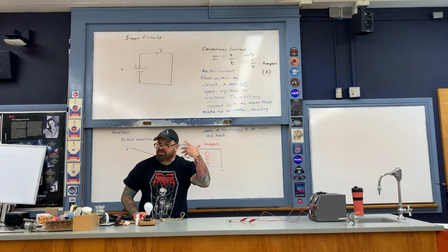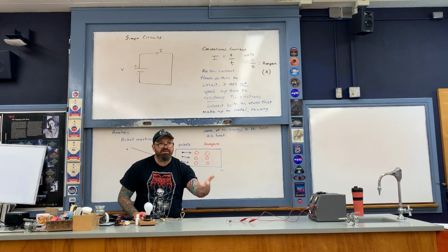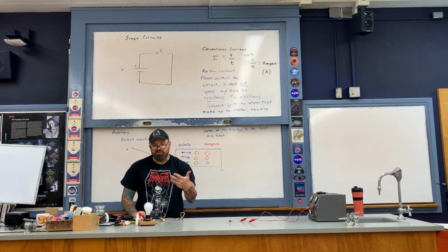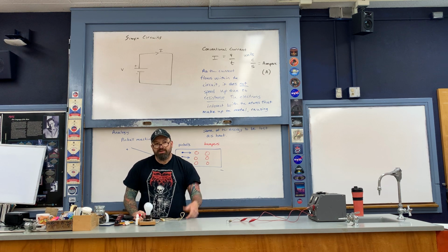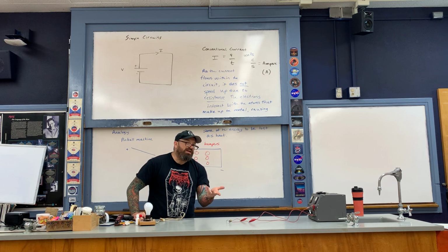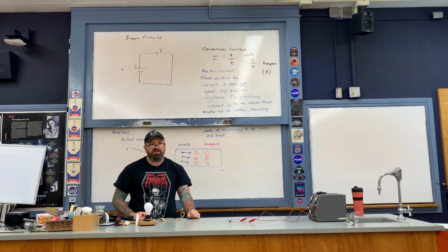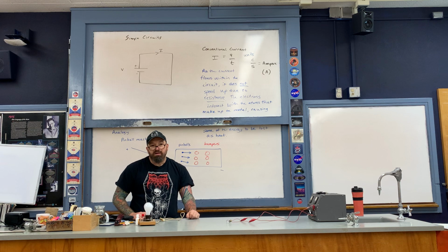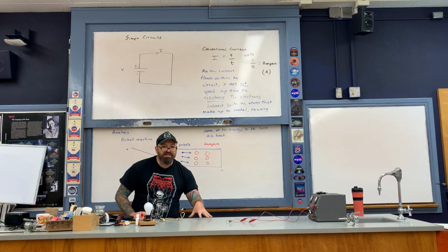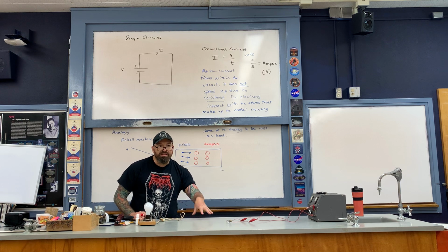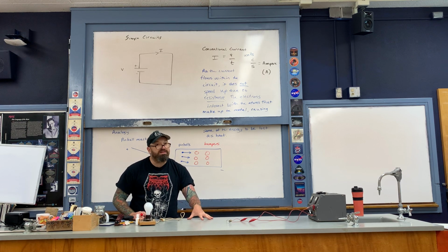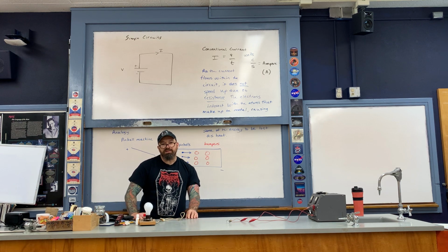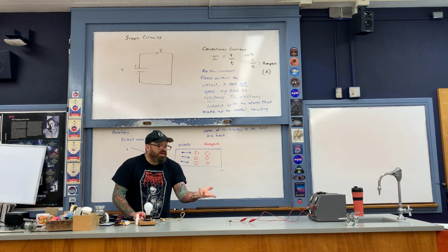So we have this idea in our heads that the current is just racing through electrical wires because we're somewhat fearful of electricity, but that's actually not the case. The actual speed of the drift of the conventional current is quite small, usually less than 1 millimeter per second. However, the motion of the individual electrons themselves is about 1 billion times that amount, which is several tens of kilometers per second. However, as I said, they don't get very far.